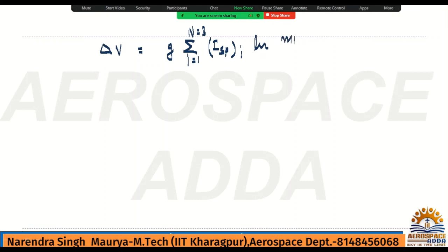I told you m naught is the total mass before operation, and mf is the mass after the operation when the propellant is completely consumed. So for mf, that formula, if you check in my previous lecture, is derived as m naught minus mp. This is the mf value. All right, done.